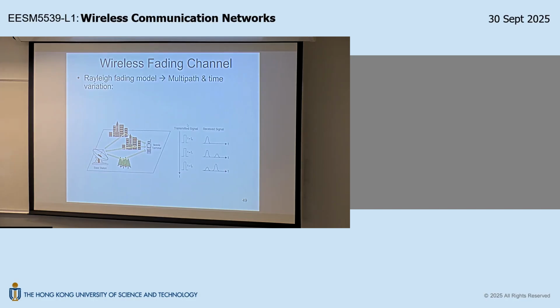If we are moving over a certain terrain, like this, do you expect the receive power will now be a constant? Again, probably using your common sense, it is unlikely, right? So you still expect the fluctuations, right? So that means there must be another process beside 1 and 2, right? That drives the signal fluctuation.